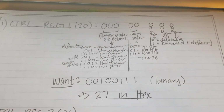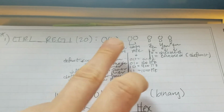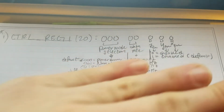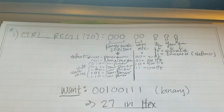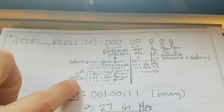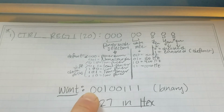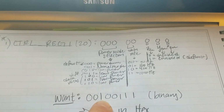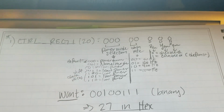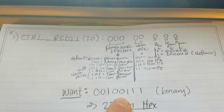So basically, these first 3 bits, like I had mentioned, are the power mode selection. Assuming these are all zeros, that's what your binary would look like, just a series of 8 zeros. That's not super interesting. So what you would do is look at the data sheet again to figure out what the different modes are. I see 001 is normal mode, so that's what I want. My first 3 bits are going to be 001 to tell the sensor that I want to operate in normal mode. The data rate that I would want is 50 hertz.